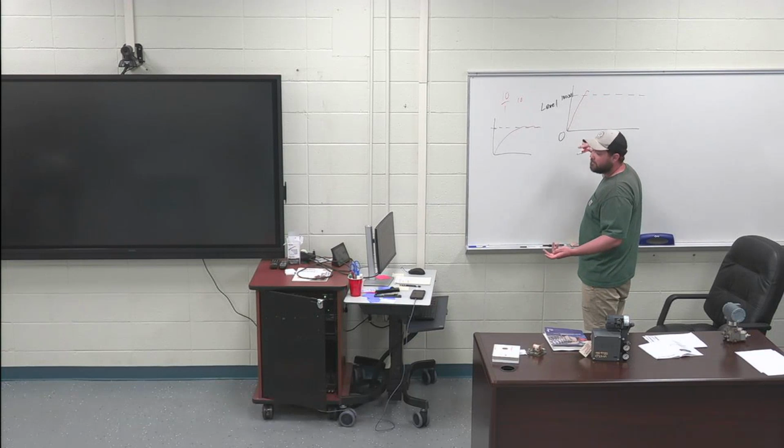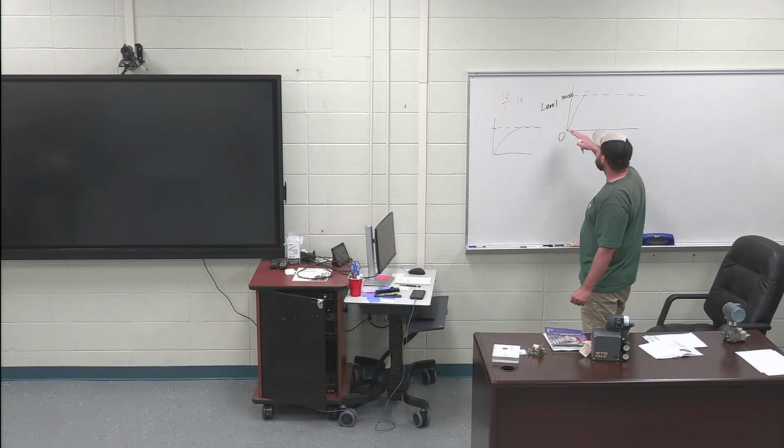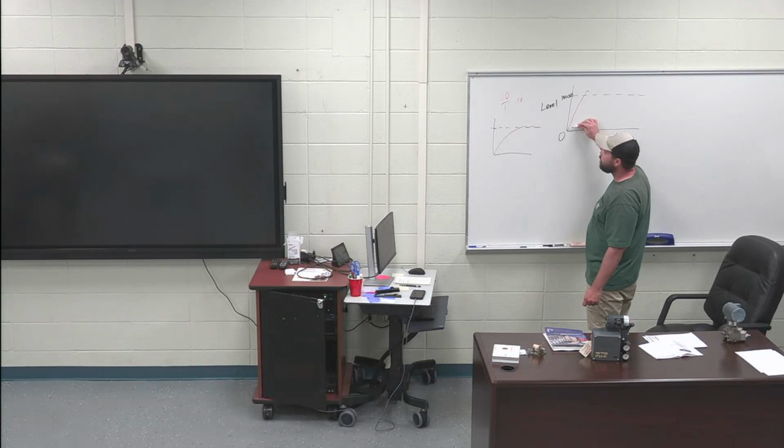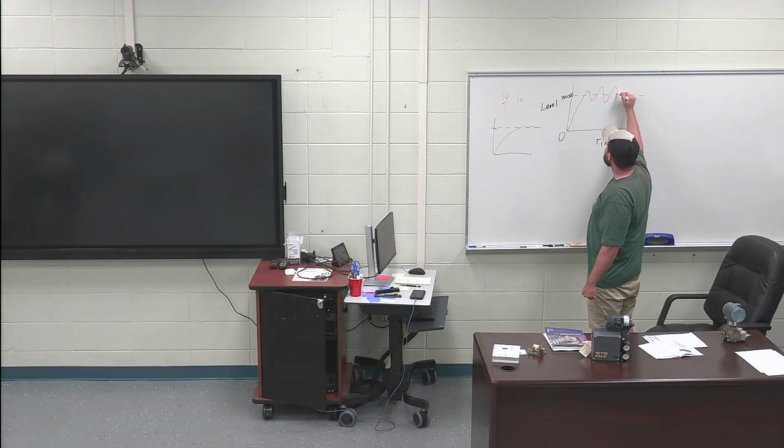That's why it's good to have an analog signal from 4 to 20. If the gain's too high, it can send a 4 milliamp signal saying go all the way open. And if it passes it and the gain's set too high, it can say put 20 milliamps on it and it's gonna go too far down, and that's where you can oscillate like this.